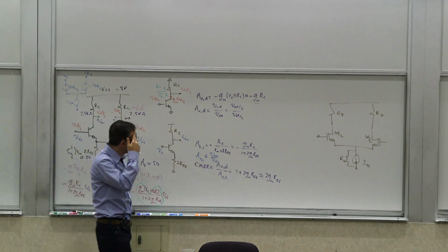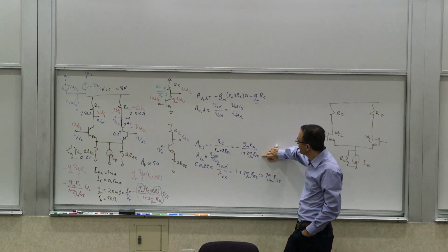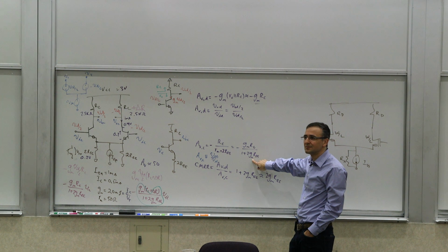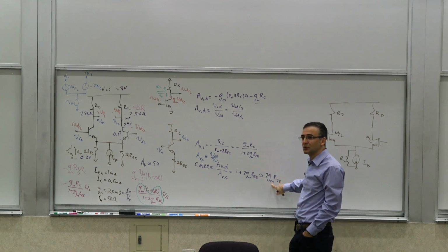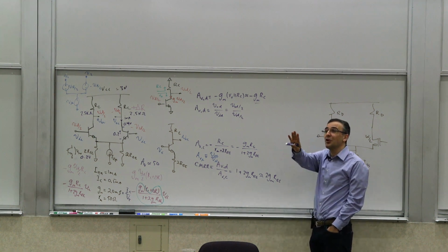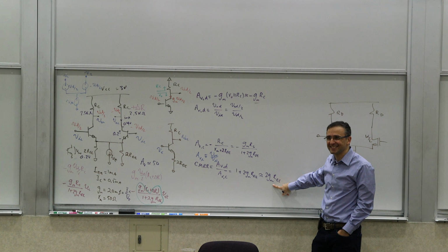Your common mode rejection ratio goes down when GM goes down. Why does it go down? You're saying the GM is going down, right? I mean, right below you have the equation. So you're concerned about the GM part of it. That's good, it's good conversation. So GM is going down, right?